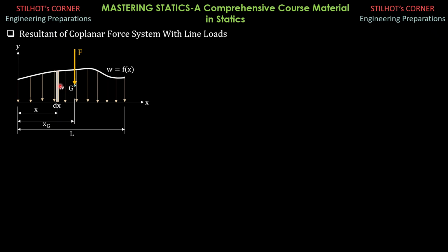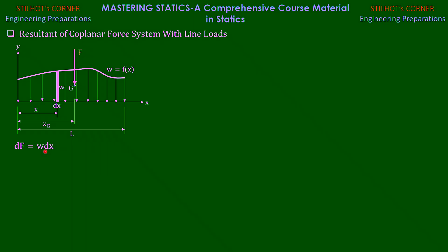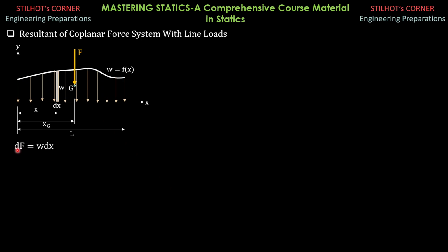And the force on this rectangular strip is, of course, the differential force dF. So dF is the area of this rectangular strip, which is thickness times the height of the strip. So integrating F therefore is the integral of this W times dx, which is the integral of differential area. So therefore, we interpret this total force F as simply the area of this line load.